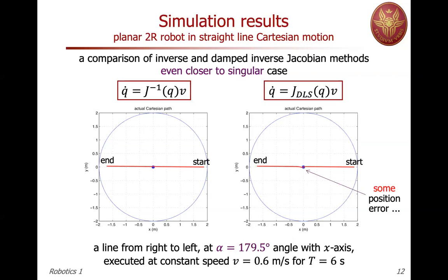What ensures us that this matrix works like a Jacobian, and so it's super, okay? No, it does not ensure that it works like a Jacobian, in the sense that if I could invert or pseudo-invert the Jacobian, I would generate exactly the desired velocity. Here, I know for sure that I will generate an error, okay? So the trick is, what is the best compromise with the lambda? So it's lambda different from 0, but not too large, so that you keep the joint velocity limited, and still you're getting close to what you would like to do.